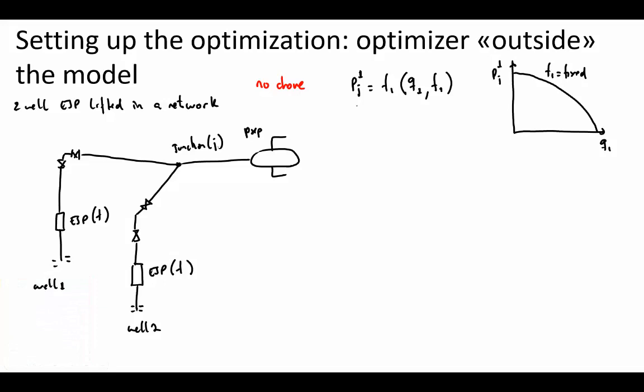The pressure at the junction is calculated from here: you have PR, you fix the rate, you calculate PWF, then through the pump you calculate the pressure out of the pump, then the wellhead pressure, and then the flow line gives the junction. So this equation has the IPR, the TPR, the ESP, and the flow line, FPR.